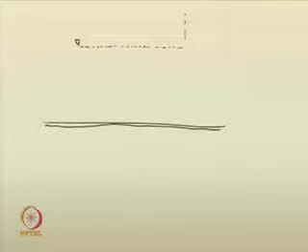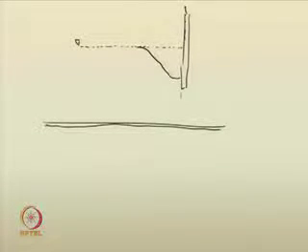How? I am just elaborating the cross section now. This was the original depth of flow in the channel. The sluice gate is raised like this. When it was raised, the water dipped to this location and the negative surge is propagated.